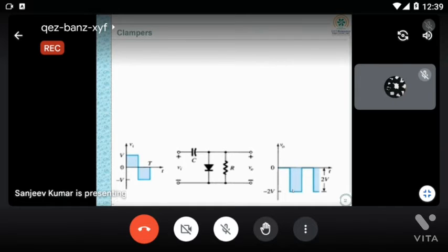So logically, if I take this line, the origin is here. Now I'm taking the origin to this position. So I'm taking this as 0. Automatically this will be V and this will be minus V. So what we are doing here is, you can see this is your DC level. Now we are only shifting the DC level to this position. Are you getting me? So this DC line or DC offset you are changing. Otherwise the voltage swing will be the same.